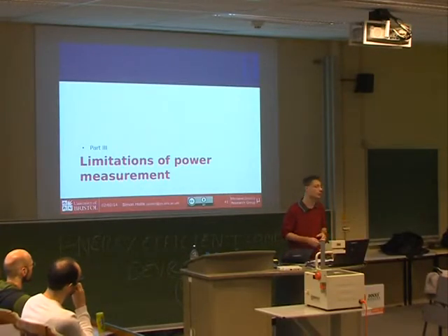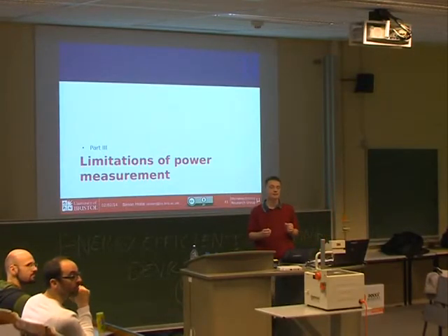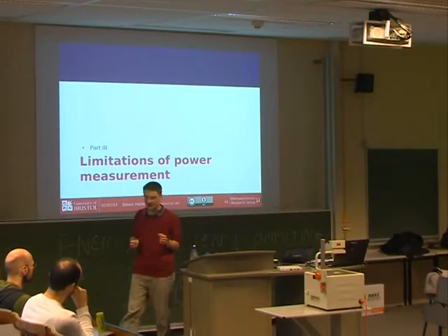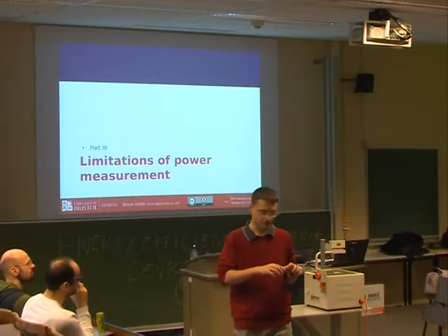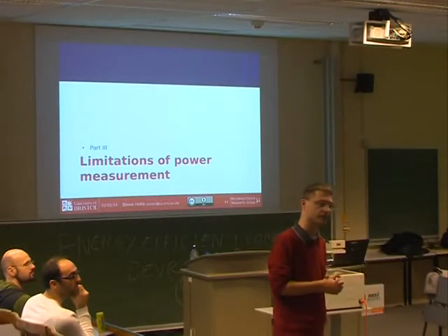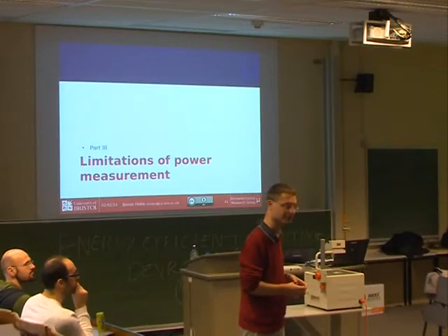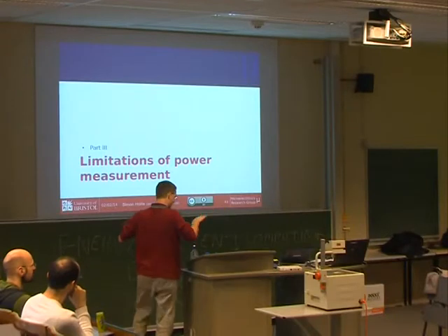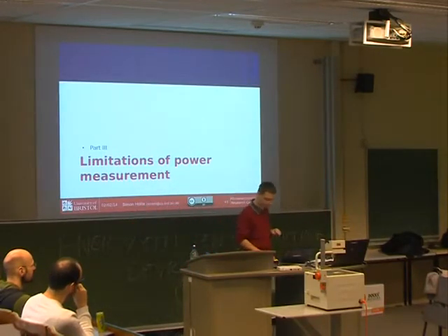So the shunt resistor is something with 0.1% reduced error. What about non-linearity of the ADC? Do you take that into account as well? That will be specified in the data sheet. Typically, they are internally calibrated to produce a linear output when you get the binary representation. But these kind of things depend on the ADC that you use, and you have to read the data sheet. It's always a caveat. So you normally get a linear binary representation, even if it's not a linear response from the ADC itself.